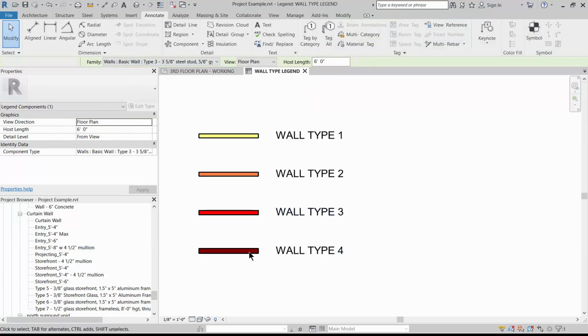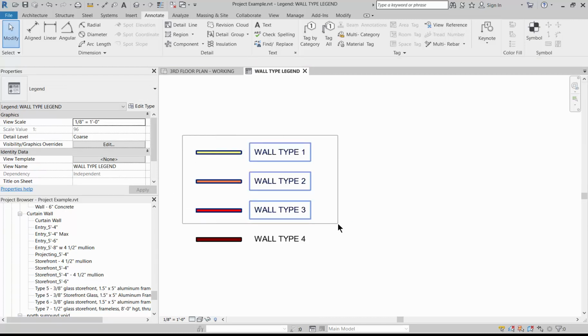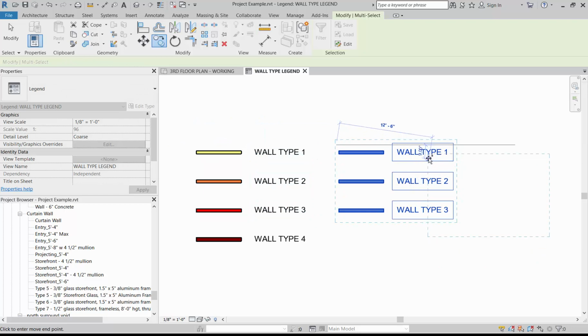And double check all the colors are showing up appropriately, everything is checked correctly. Now what I'm going to do here, because all of these 3 wall types then have an option with the glazing in them, I'm going to copy this over.